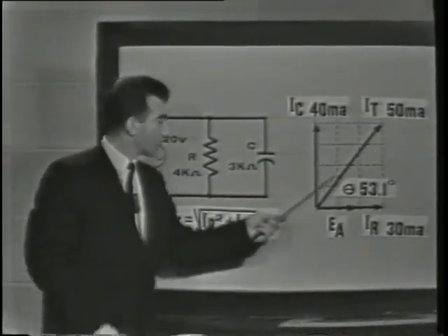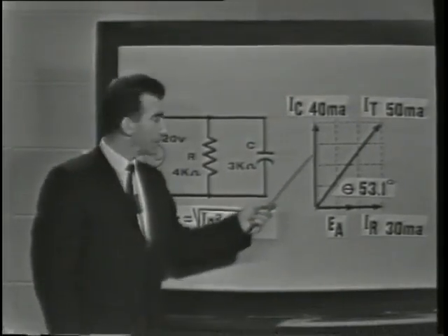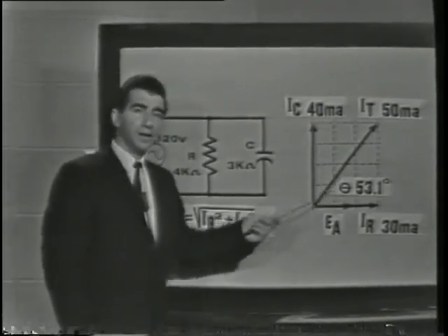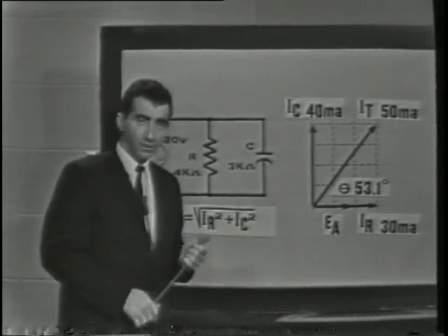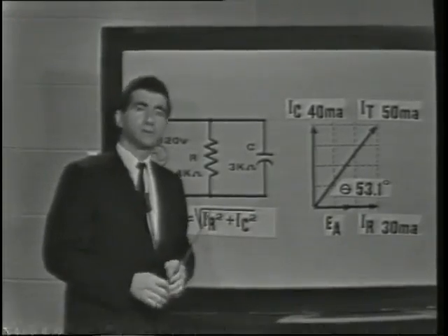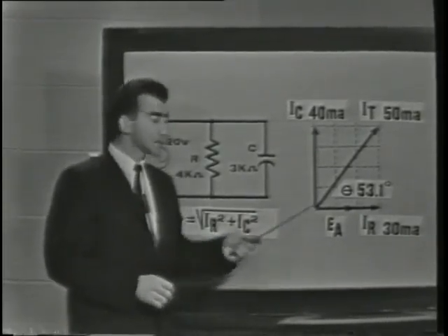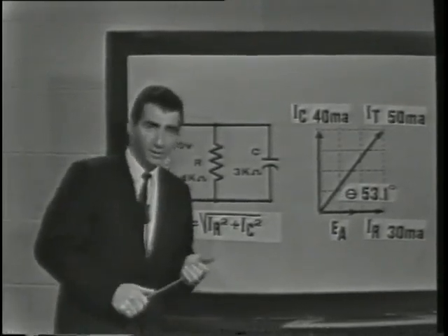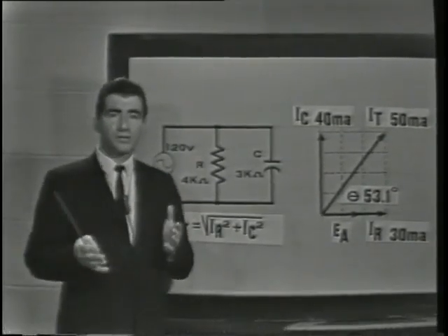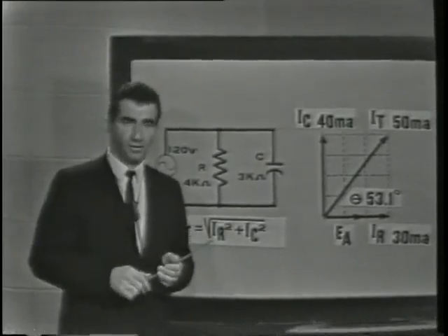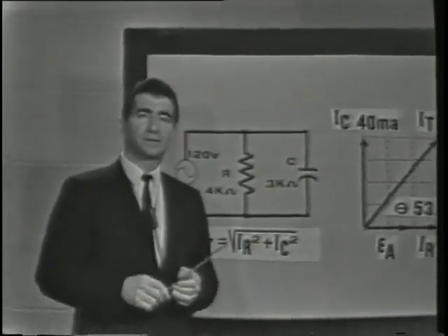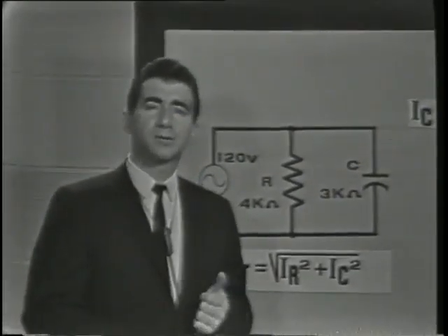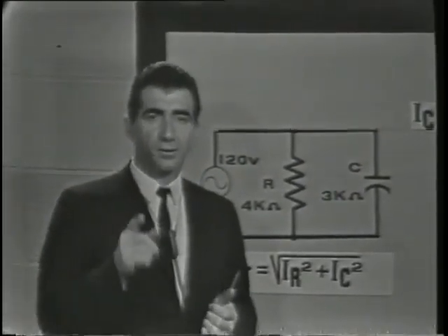And the phase angle can be determined, once again, by simply measuring the graph, or, more exactly, by calculating the sine or cosine of angle theta, or the tangent, and using the trig tables. The phase angle is important to us because it gives us an indication of the power factor, which we defined as the ratio of true power to apparent power. Now, the facts we've discussed concerning this circuit will become more important to you as you gain additional knowledge of their application. So know them well.